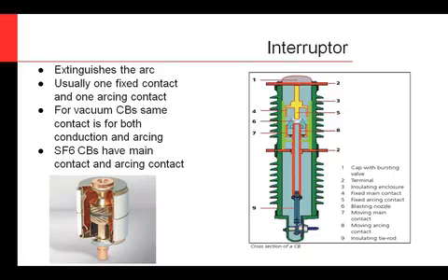You're getting very, very large amounts of heat in there. And so the arcing contact is actually designed to wear away in service and protect the main contact. And there are some tests you can do, such as dynamic resistance measurement and different things to check on that and make sure it's not wearing away too quickly.